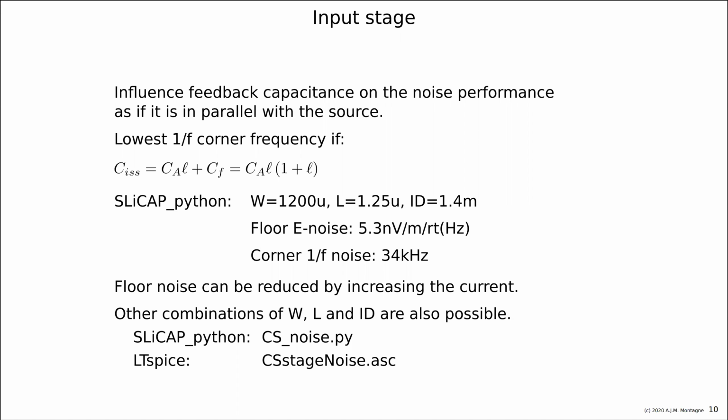The Python and the LT-Spice. The LT-Spice is just to show you a few things that are happening with a model, with this BC model that we use. But of course, basically you could do all the noise design and the signal path design in SliCap. And only at the point that we need nonlinear stuff like the drive capability, or we want to analyze the distortion, then we need to go to LT-Spice.